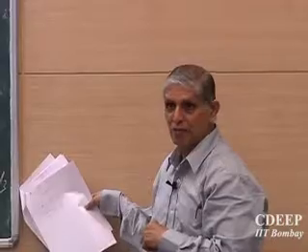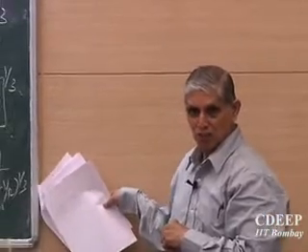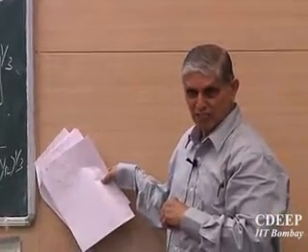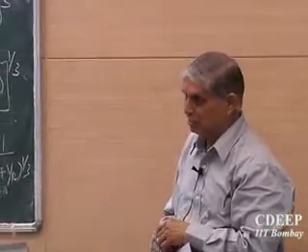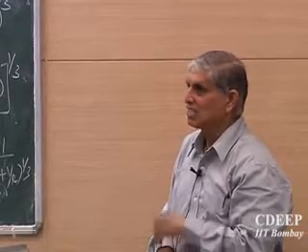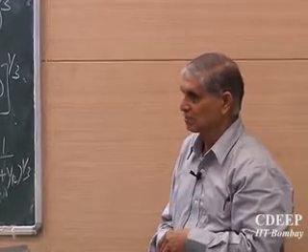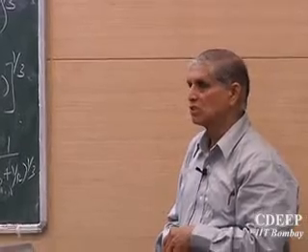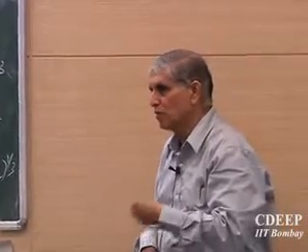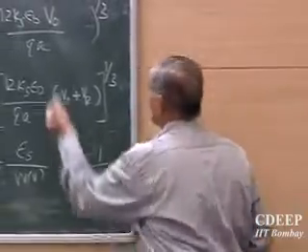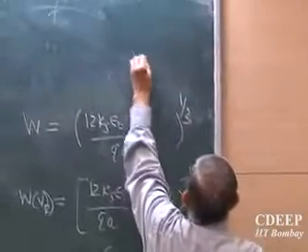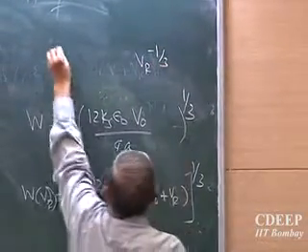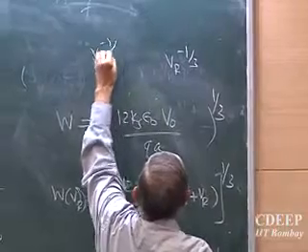Earlier what was the formula given here? Half. Step junction, this was half. In the case of a linear graded junction, it is 1/3. So what is it, faster changing or slower changing? Is capacitance with voltage changing slower or faster? So here VR to the power minus 1/3, and in the step junction it is this.